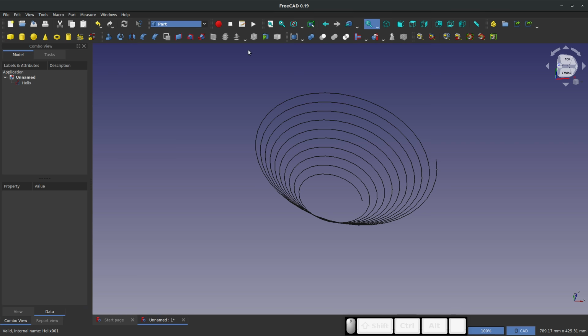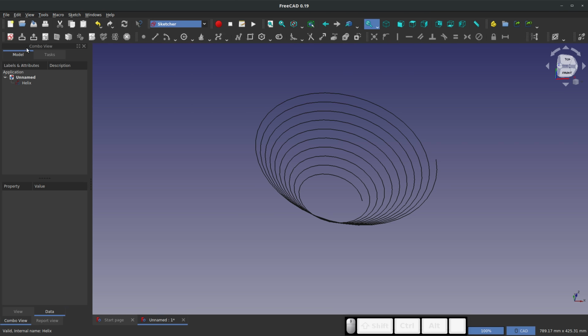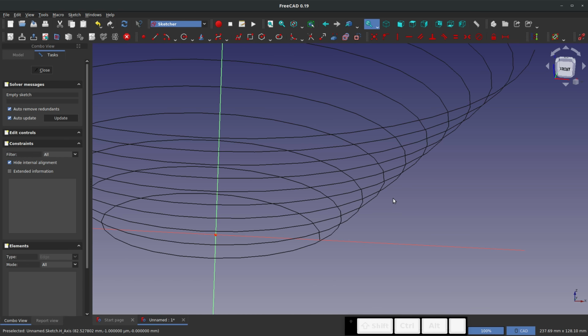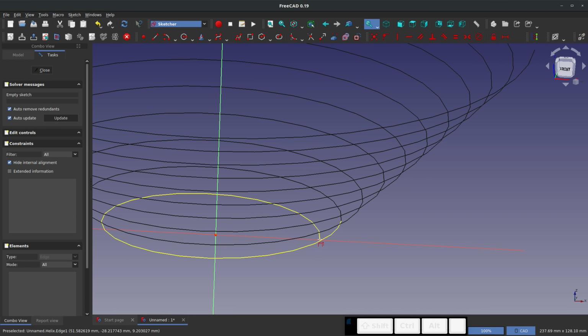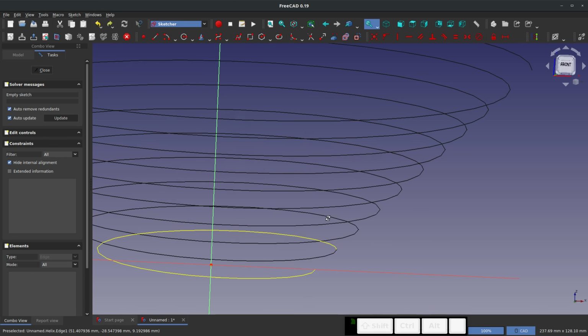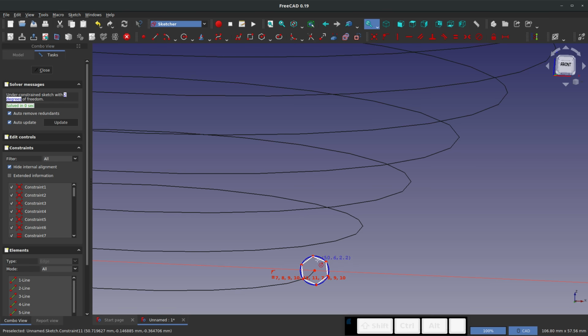And if I create a sketch now, of course I have to do it on the sketcher. And we would care about the ZX plane. Then I can even import that and it will lay flat, but I can import just that little end there. And I can choose something cool, like maybe a hexagon would be interesting.